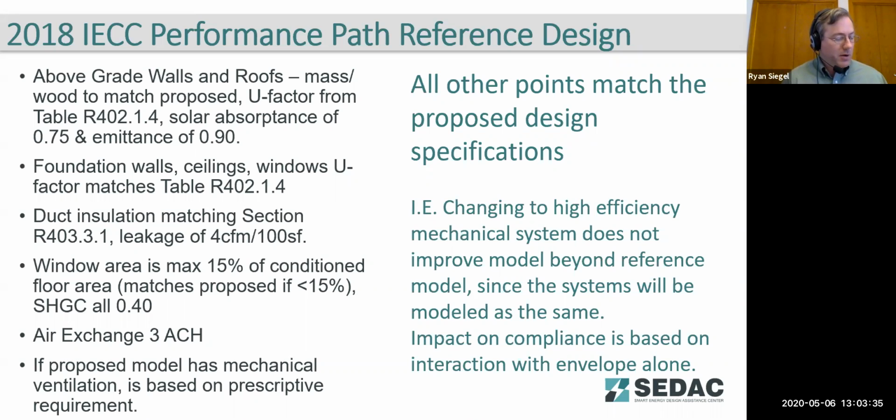The tables called for in the code state an R20 in the walls or R13 cavity plus 5 continuous for wood framed walls. Mass framed walls have a little bit different lower values, and then ceiling is an R49 for residential buildings. So those are the tables here. I believe the difference, there's an Illinois amendment which includes City of Chicago, is for basement wall R values.